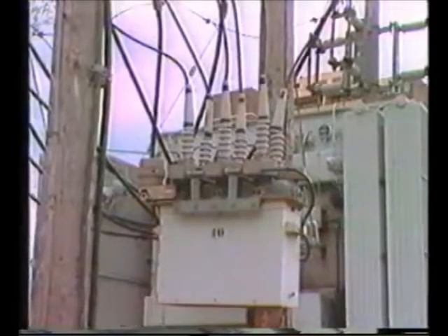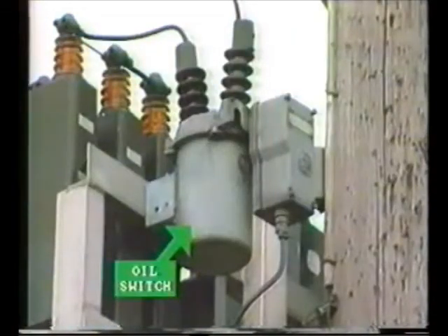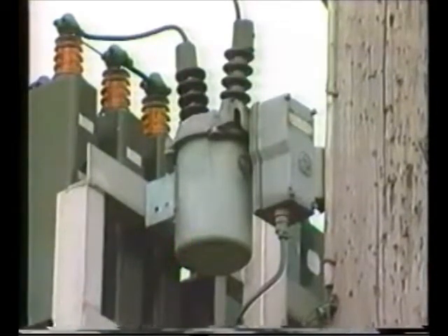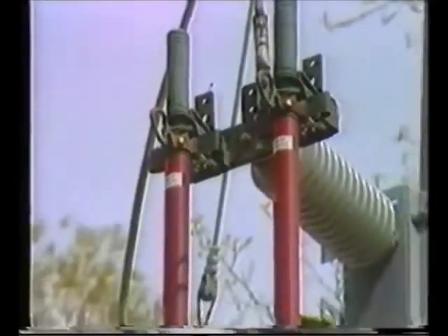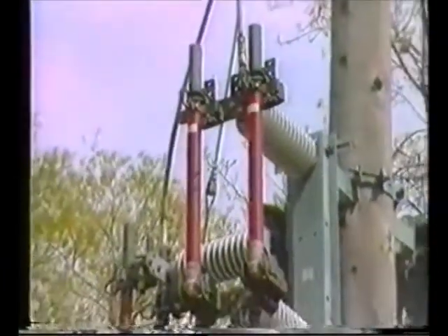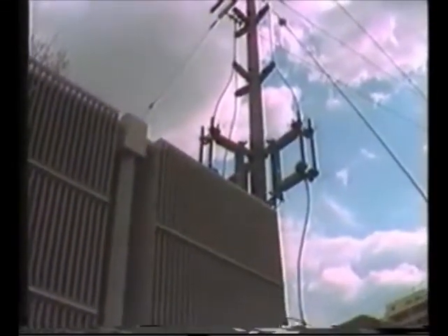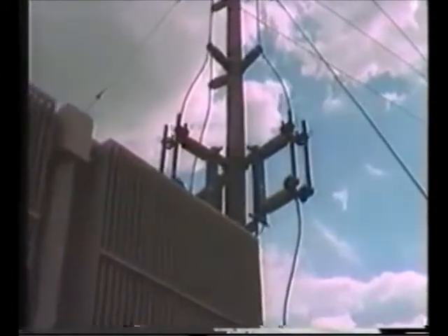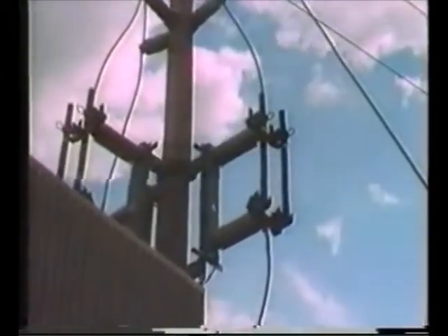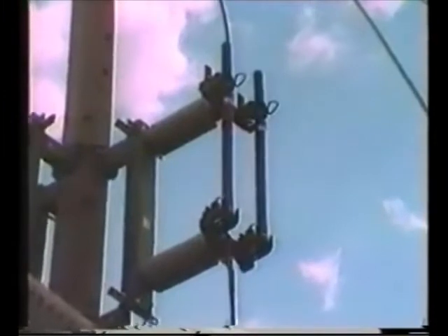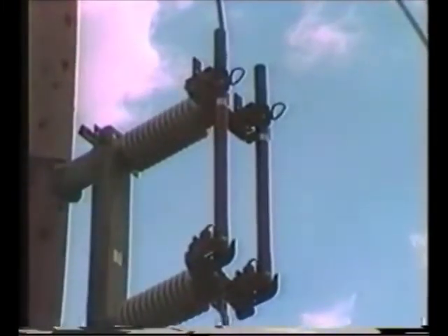There are many other switching devices, particularly in use on the distribution system, such as reclosers, sectionalizers, and oil switches. But in general, these are capable of very limited fault interruption. On the distribution system, fuses are often used in place of the relay circuit breaker combination. The fuse is not so fast or accurate as protective relays, but it does provide satisfactory economical protection for distribution transformers and feeds.